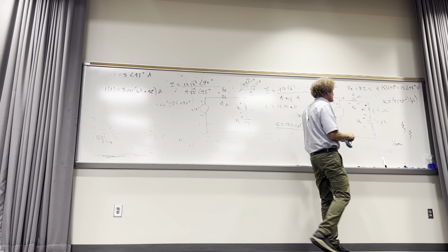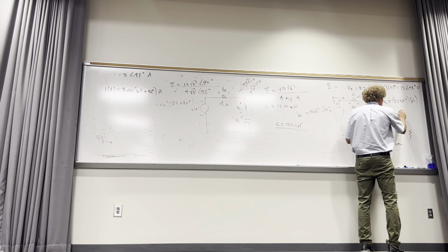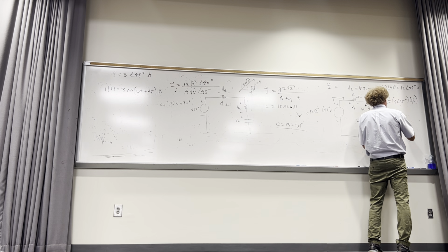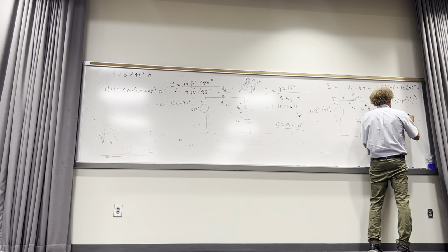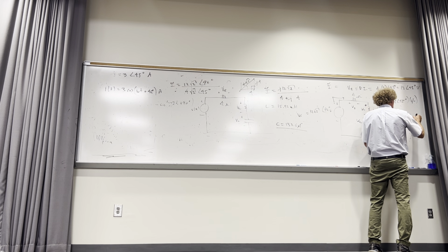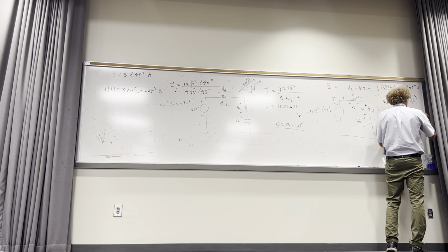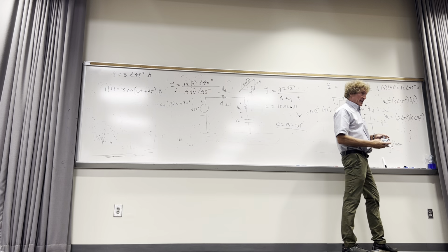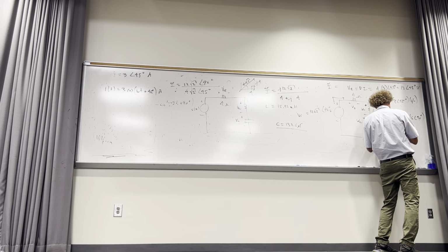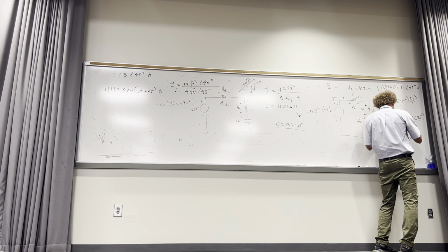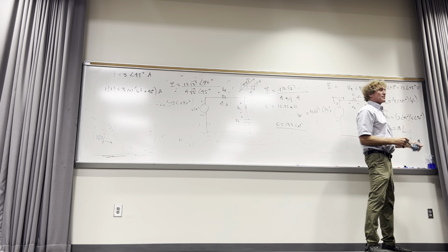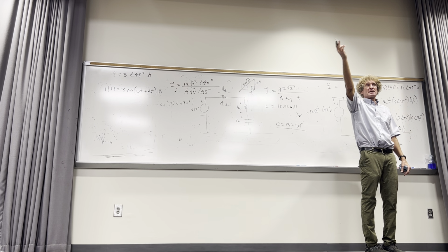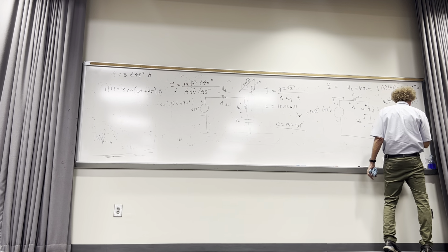So I can say the voltage right here across this would be equal to 3 at an angle of 45 degrees, times 6 at an angle of 90 degrees. The only thing you do is multiply the 6 and 3, get 18. And for the angle, you add the 45 and 90, or 135. How many can see that? Far back there, guys. All right, so that's 135.